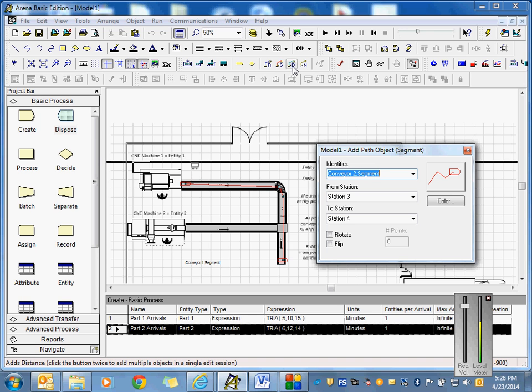And then routing actually does it by sequence, or it does it by priority, or it does it by a lot of things. Routing typically doesn't have to be associated with a conveyor belt or a forklift or anything. Always think of segments when you think about conveyor belts, like segments of conveyors. Always think about distances when you're thinking about transporters, like forklifts and carts and things like that. And when you think of routing, think of parts that require certain sequences. Like I have to machine the part, deburr the part, then paint the part. But if it's this part, then I have to drill a hole, deburr, and then paint. So it varies by 3 different things.